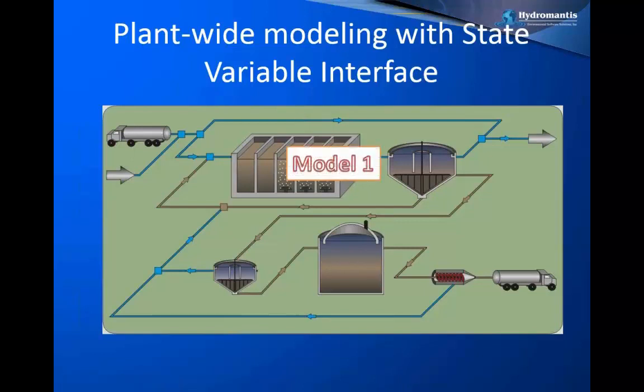In the first approach, we have the models for, for example, the activated sludge tanks, or the liquid train models, in which we are mostly modeling heterotrophic bacteria, nitrifiers, and some of the substrates like slowly degradable and readily degradable substrates. So there are some states which are modeled in the liquid train, and they are done through a well-defined model like the activated sludge models.